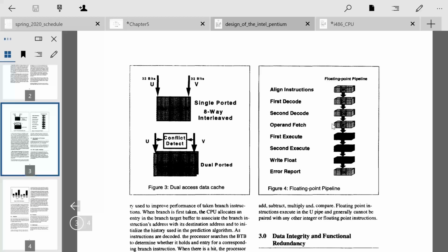So you have one giant fetch that you do for instructions, and remember with a 486 we said in the pipeline that you actually don't do the fetch on every cycle, because you pull 16 bytes and chew on that and pull instructions from it, and then once you're done pulling instructions from it, or you encounter a jump, then you pull a new 16 byte chunk. Okay, and the Pentium does that, even though they went superscalar.